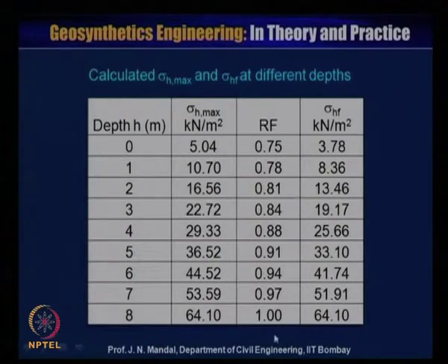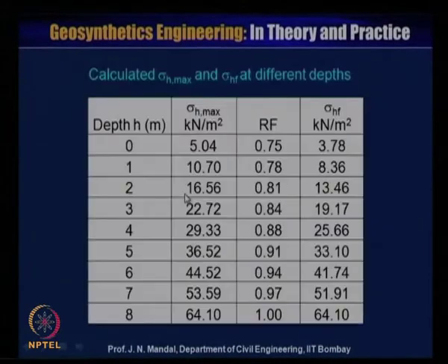So at all depths you can calculate the sigma H maximum, you can calculate the reduction factor, and equally you can calculate the pressure at the facing. Now I can show you the relationship between the depth and the maximum pressure, and between the depth and the pressure at the facing.